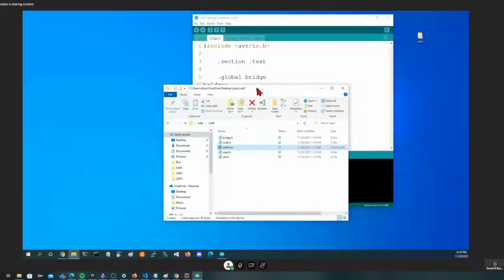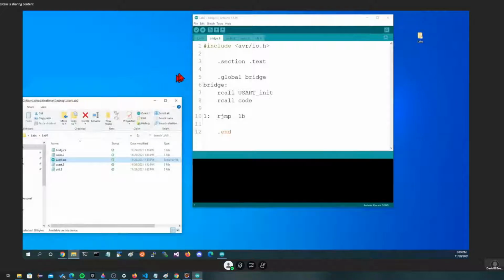And we actually do that because the very first statement is a preprocessor statement. It says include from the include library whatever file is at avr/io.h. Now, io.h is a generic file for including all of the headers for all of the CPUs, microprocessors, that Arduino supports. Inside it, it tests to see which one you're using, and it gives us the one that we need.